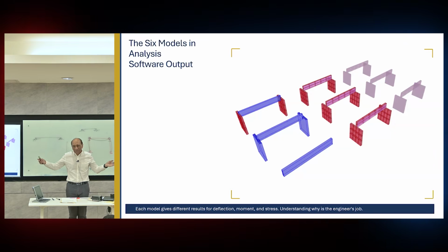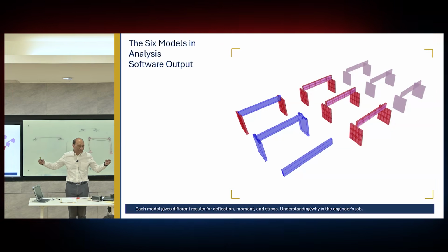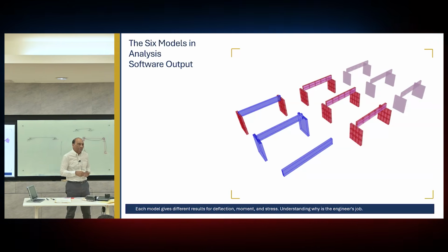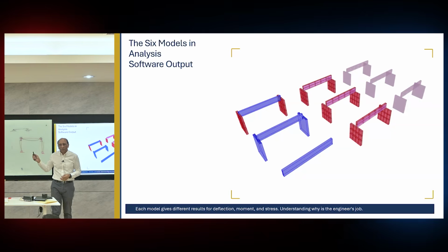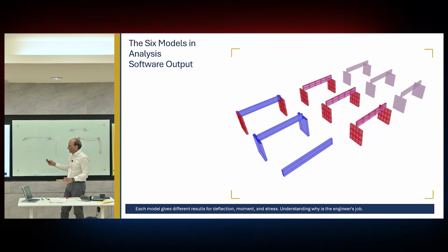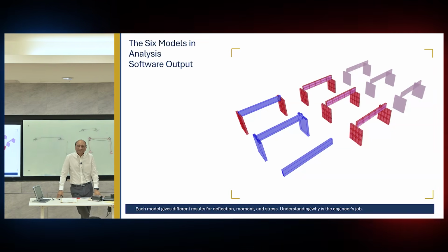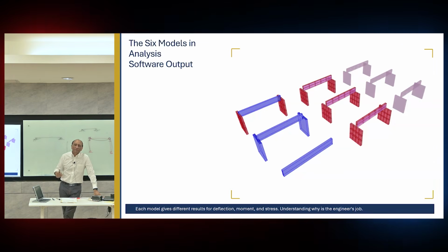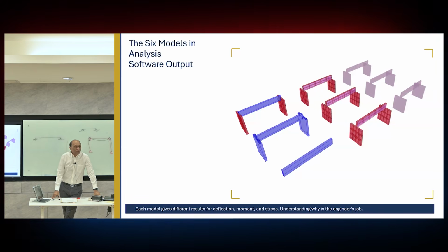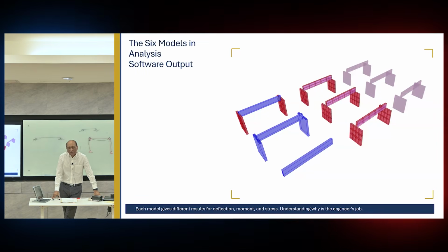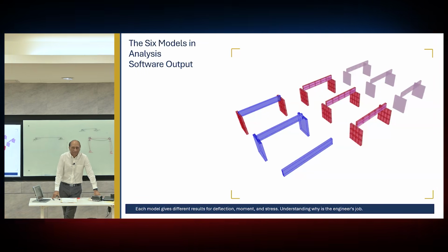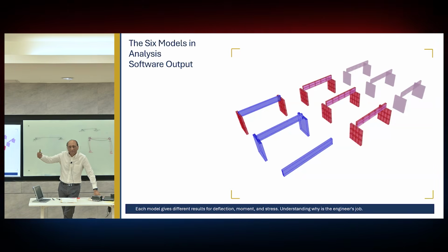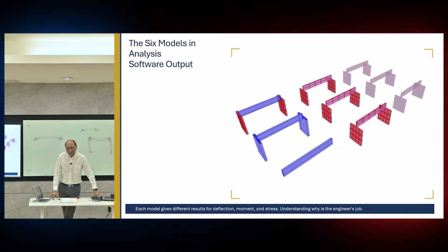But actually, that's not true. When it expands, it should expand alone after some time. Slide and then expand. So all of these issues in these 6 models, even with all the refinements that I could do, still not done, right? So the point is you must think about the behavior. What is it that you want to capture and make the model accordingly? If you just want to get the bending moments in the beam, first model is very good. Anything more than that, then each model will give you more, but not all.